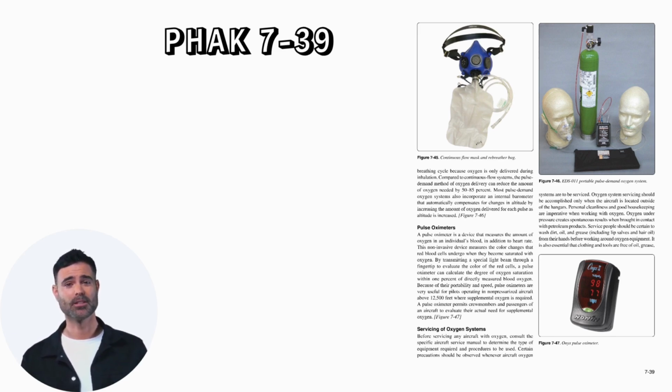Servicing of oxygen systems. Before servicing any aircraft with oxygen, consult the specific aircraft service manual to determine the type of equipment required and procedures to be used. Certain precautions should be observed whenever aircraft oxygen systems are to be serviced. Oxygen system servicing should be accomplished only when the aircraft is located outside of the hangars. Personal cleanliness and good housekeeping are imperative when working with oxygen.